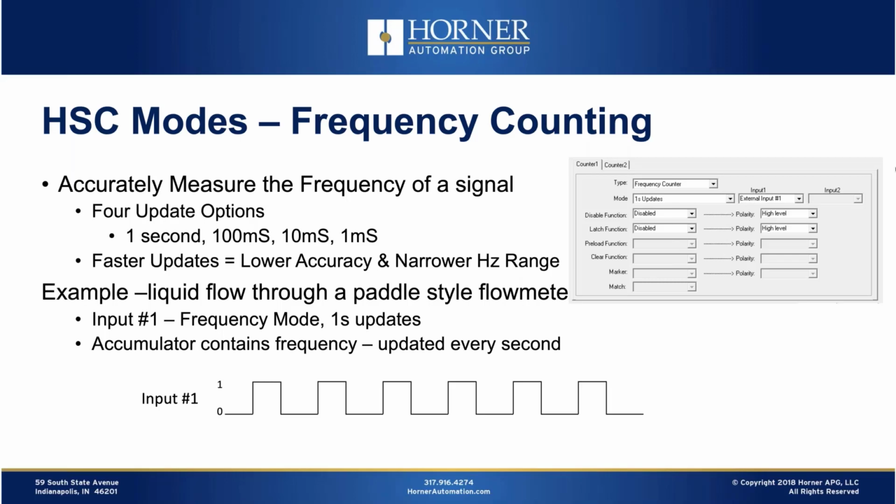I'll be able to take that frequency in my logic, and then using a conversion factor based on whatever is in the documentation for the flow meter, convert that frequency into a liquid flow. Okay, so that's a pretty simple example for frequency counting.